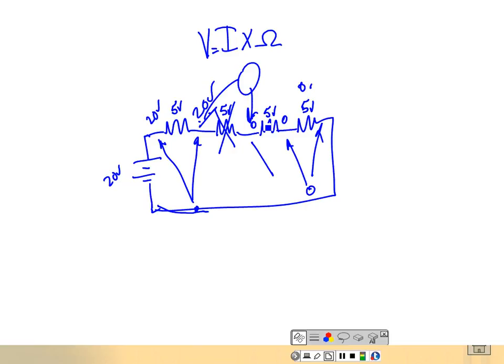And that's one of the hardest things. If I measure across a good fuse, I've got a circuit that's got voltage applied to it. If I measure across a good fuse, how much voltage should it drop? Practically none. It's going to drop a little because it definitely has resistance, but it's very, very low, because how does it blow? How does it melt?